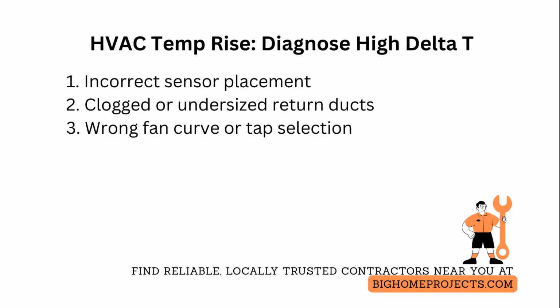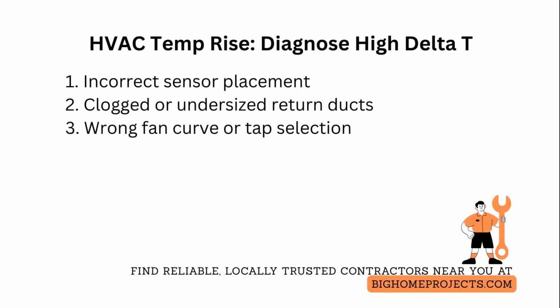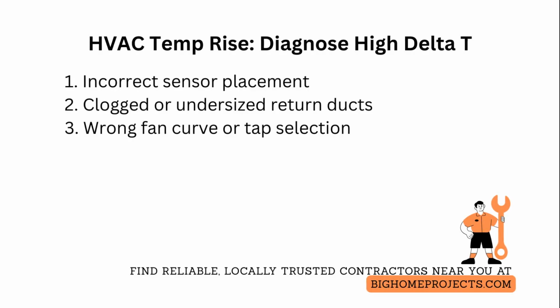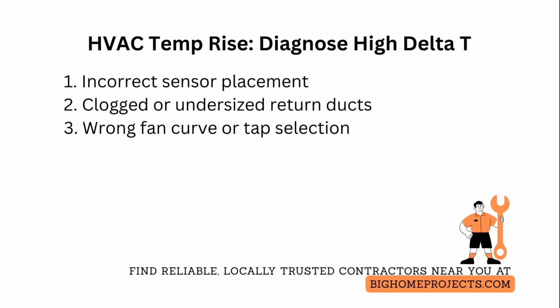One of the biggest issues is clogged or undersized return ducts, creating low return CFM and high temperature rise. Remedy by cleaning filters, enlarging or adding returns, and measuring static pressure to verify improvements.